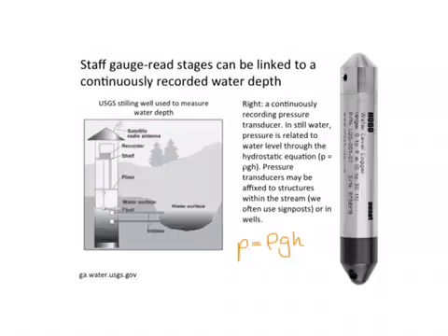Pressure transducers, however, will also be sensitive to dynamic pressure, or U squared over 2g. And so these pressure sensors are often deployed not in the stream itself, but in a reservoir that's connected to the stream, so that the water level within the reservoir is at the same level as within the stream, but there's no velocity, and so there's no dynamic head.